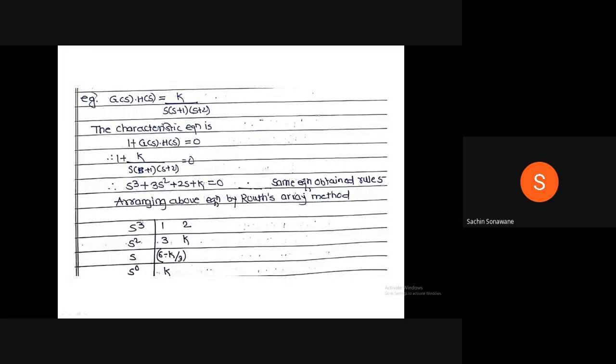Therefore, towards left side we have to write S cube, S square, S raised to 0. Now S cube, in front of S cube you have to write coefficient of S cube, first is 1. Then you have to jump to 2S, therefore 2. Now S square, in front of S square you have to write 3, and then like this K. Now in front of S what you have to do? 3 into 2 minus K into 1 divided by 3.